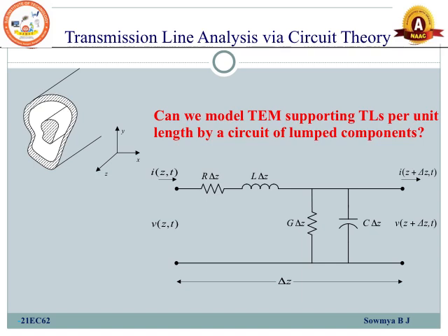Now let us have an understanding of the analysis of a transmission line by considering circuit theory. Can we model the transverse electromagnetic wave supporting transmission lines per unit length by a circuit of lumped components? That is the question. Is it possible to model the transverse electromagnetic wave supported by transmission lines per unit length by a circuit of lumped components? Yes, definitely it is possible.